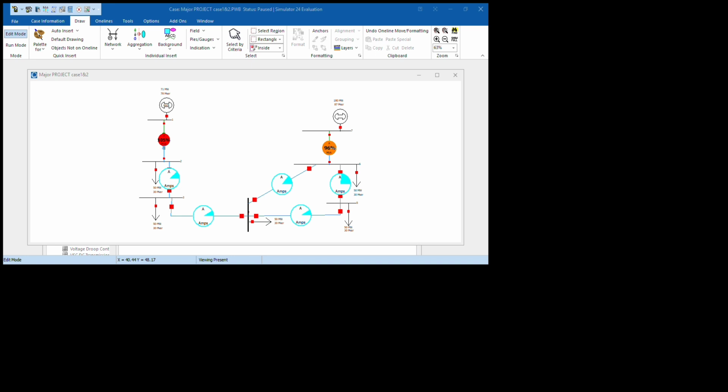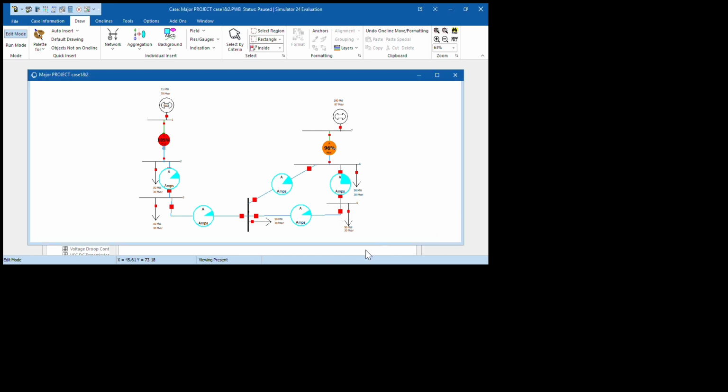Since the voltage is all the same, we can neglect the voltage ratio. We just use the new base over old base value, and we can get the new per unit impedance for each parameter. So for lines, this will be the R and this will be the X, and the susceptance will be the B, which we will be using for this simulation later.